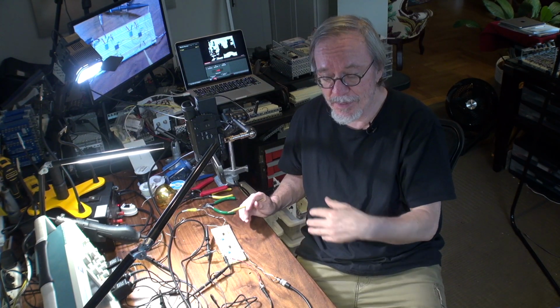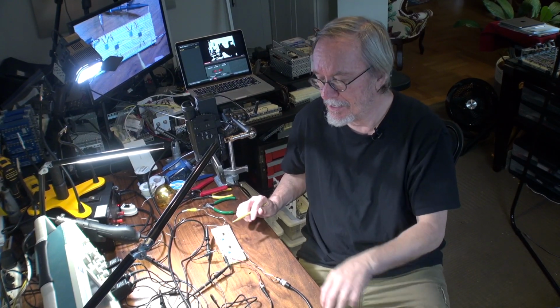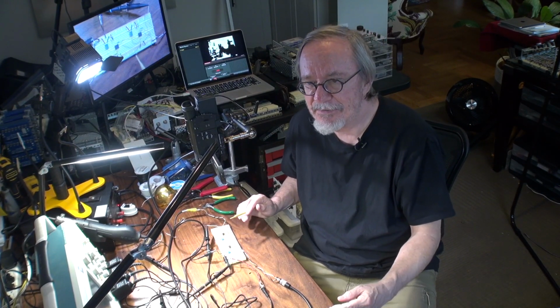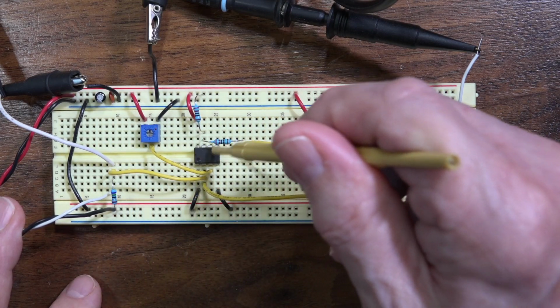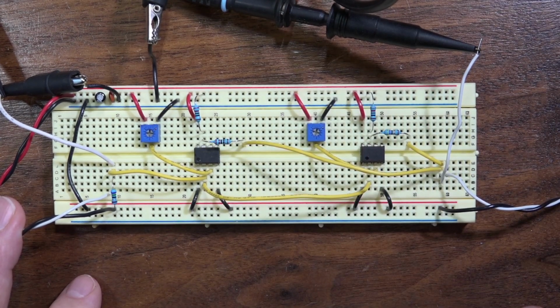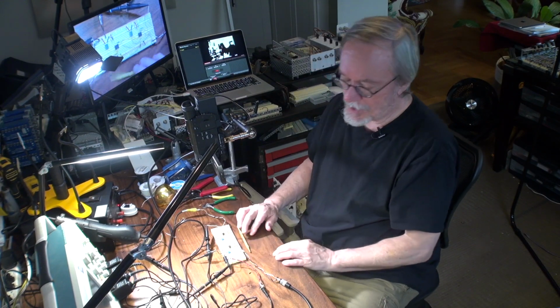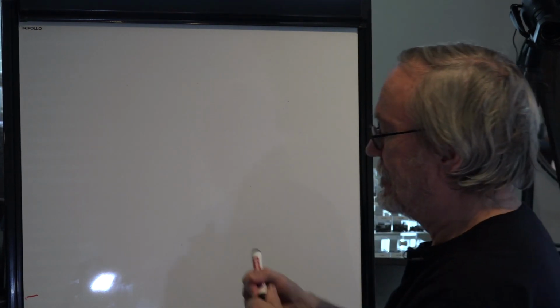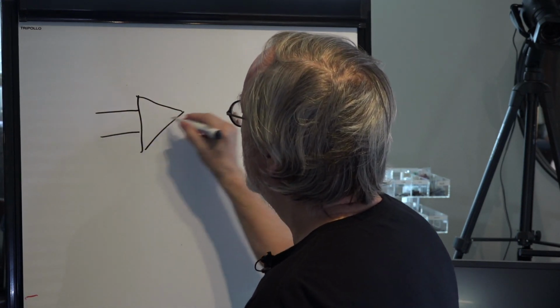Doesn't matter whether it's NTSC or PAL or anything. SECAM, I'll bet. HD, always 75 ohms. So the very first wire goes into this guy, this integrated circuit. He's an IC, he's a chip. So let's go back to the drawing board and draw this chip. What is that chip? Well, the simplified schematic looks like this, with 2 inputs and an output.